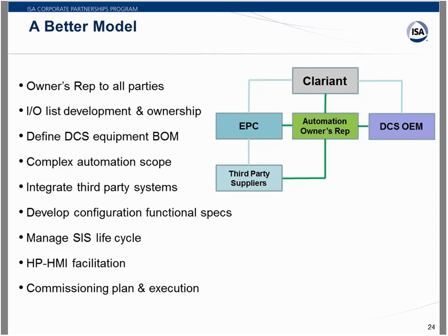The automation owner's rep also managed the safety system life cycle for this project, including tasks like performing SIL verification to make sure the design met the intended SIL level that was required by the client, development of the safety requirement specification, and development of the proof test procedures, and then helping to check out to make sure things work the way they were intended.